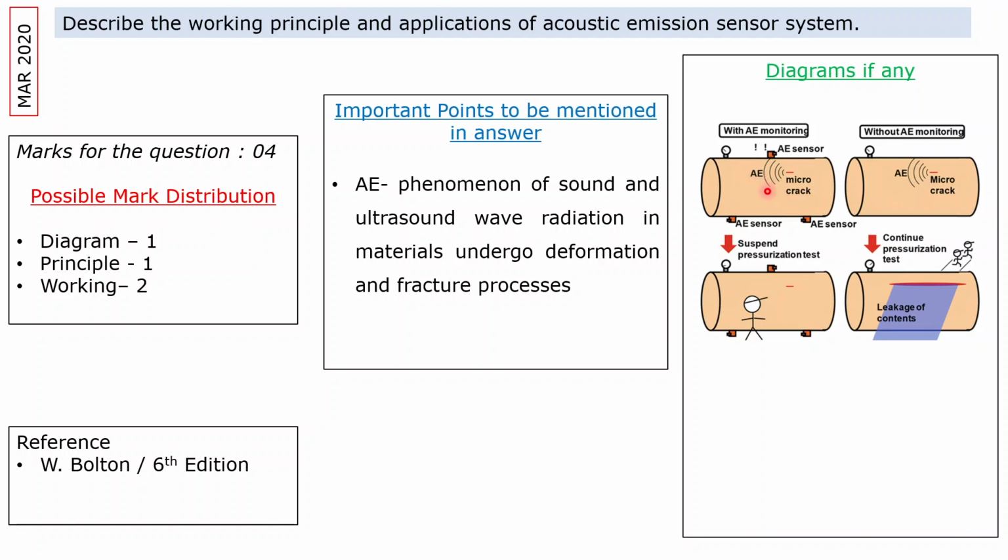During the pressure test, we test the tank using a pressure almost double the pressure rating. For example, if the tank is manufactured for 3 bar capacity, it will be tested with 4.5 bar or 6 bar, etc. What happens is that during this fabrication process, there is a chance of getting a micro crack inside the material of the tank.